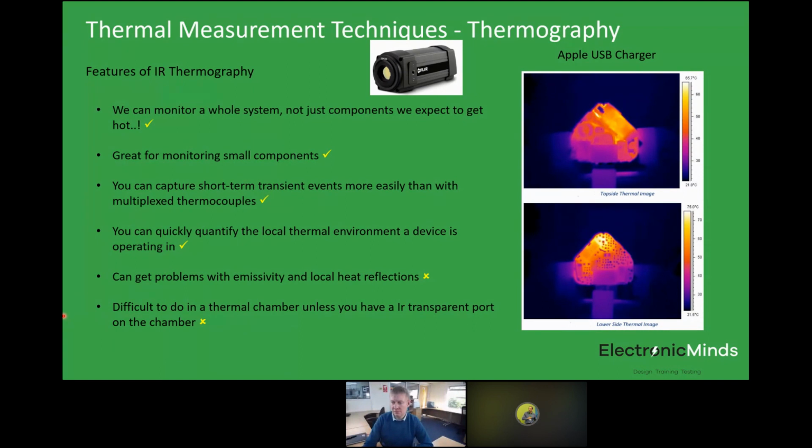If I can comment on that, sometimes when you put things operating outside of an enclosure, things are fine, and then when you put your converter into a small box because you want it compact, suddenly you have heat building up and your ambient temperature is no more 25 degrees, it's 70, 80, and you run into real trouble. Yeah, that's a very good point. That again comes back to the whole idea of what actually is ambient, and it depends. It's what is ambient from the perspective of the system you're trying to cool. And like your example there, Jose, that depends on whether you put it in a box or not. So it's really important to consider that.